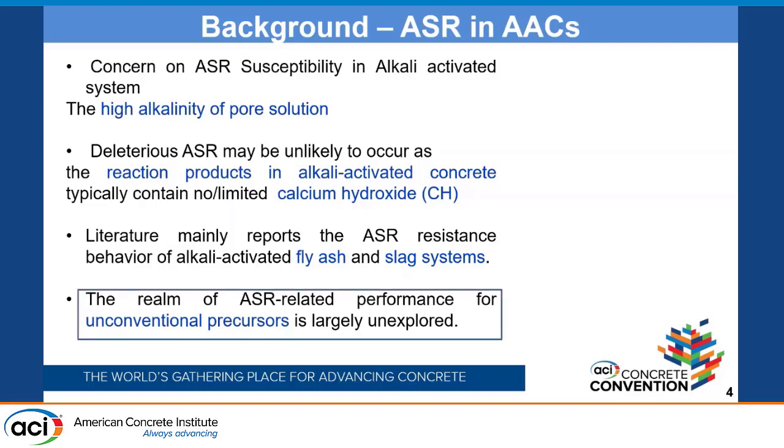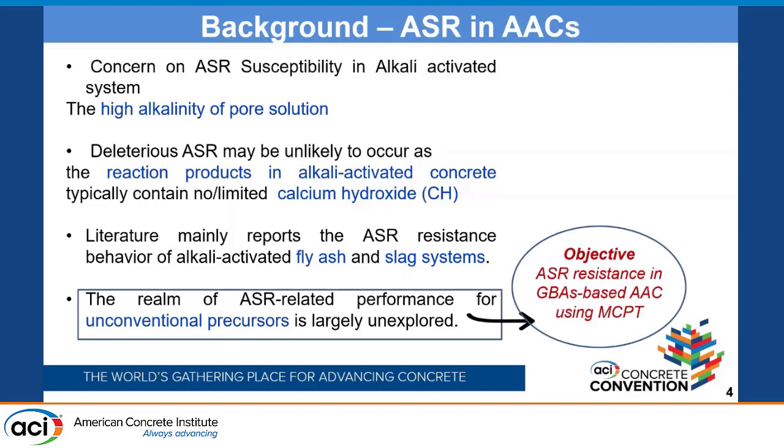But still the question of ASR-related performance for unconventional precursors remains largely uninvestigated. And here is where we get our objective from. The objective of this study is detecting ASR in ground bottom ashes-based alkali-activated concretes using the miniature concrete prism technique.